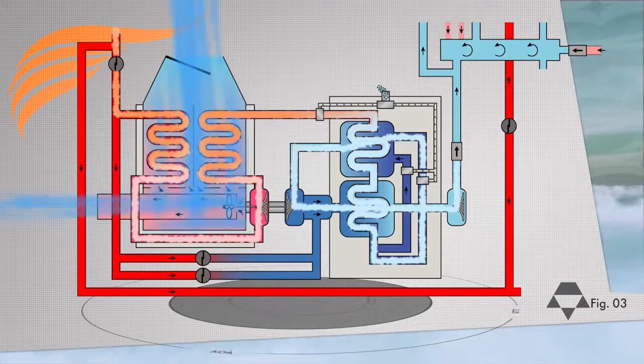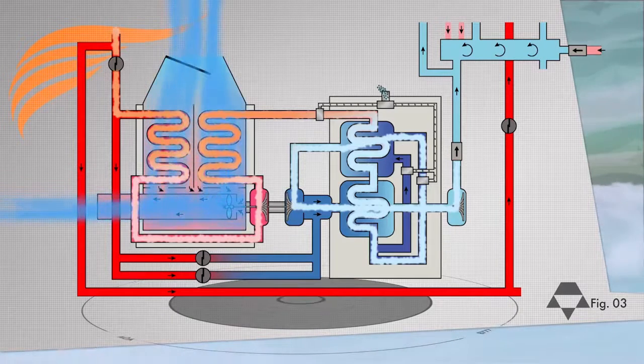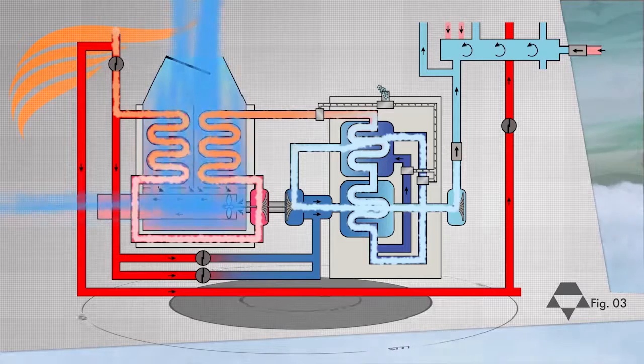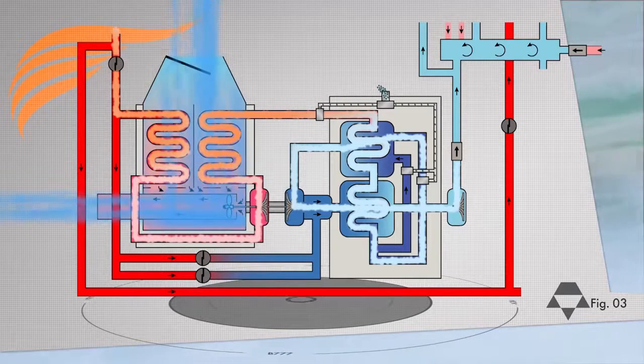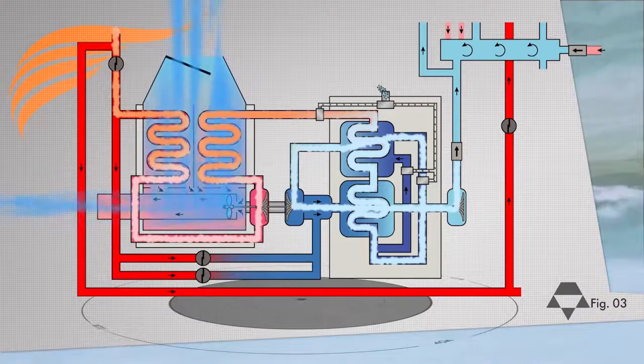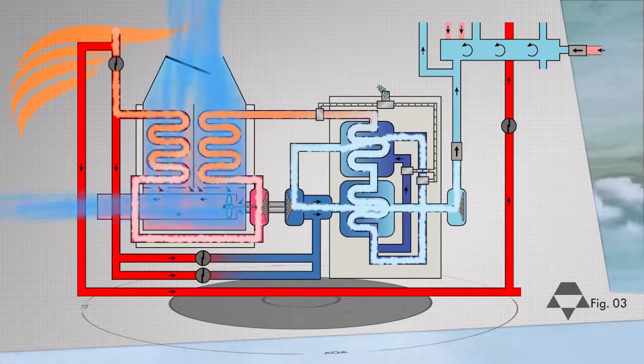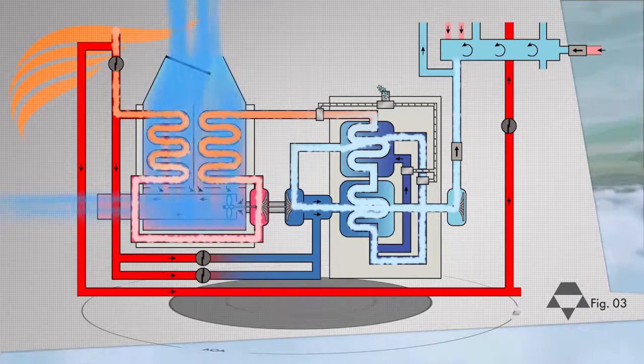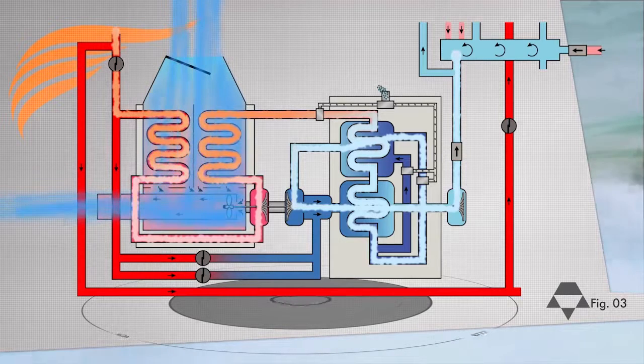The energy that is released in the turbines turns the shaft of the air cycle machine. Finally, downstream of all the components we just mentioned is a check valve. The check valve controls the direction of the flow from the packs into the mixed manifold and prevents backward flow.